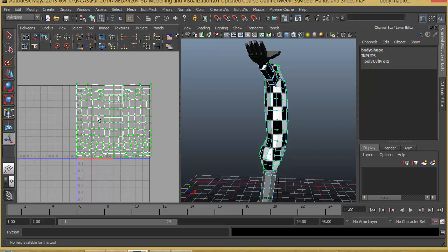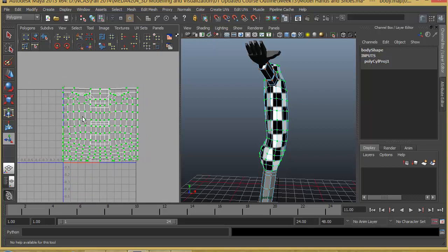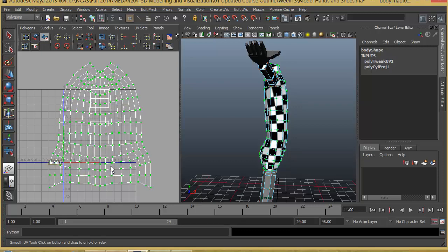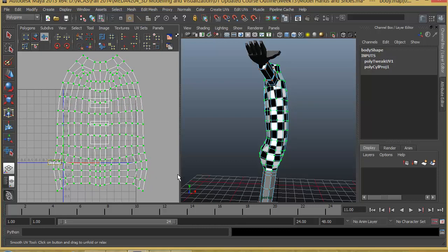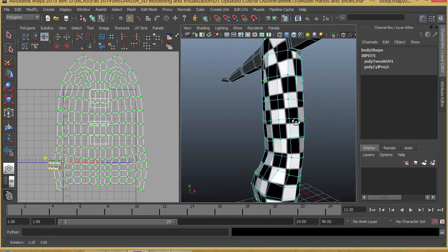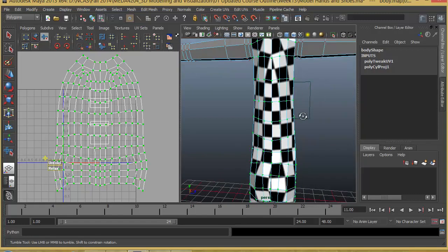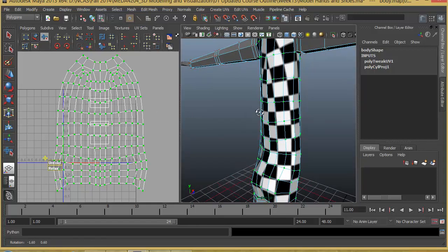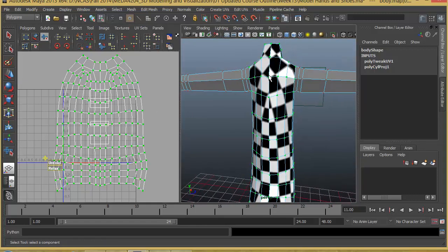Now, the unwrapping is being done by Maya through an automatic algorithm. So we can do the unwrapping by going to this option, choosing unfold. Okay, so as you can see, what it does is it basically calculates or tries to compare the vertices, the UVs that are in between, and tries to give the same equal amount of space that is here in the UV texture. So you can see that this edge that is coming here is not actually matching up with the left side and the right side.